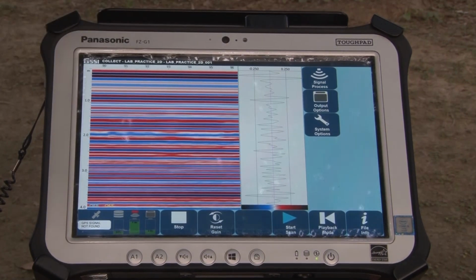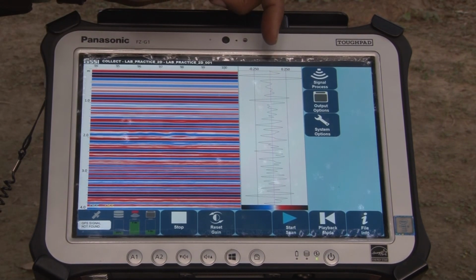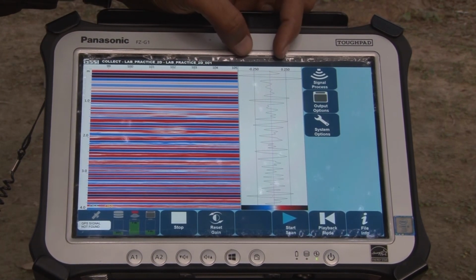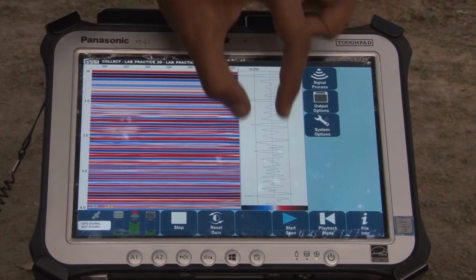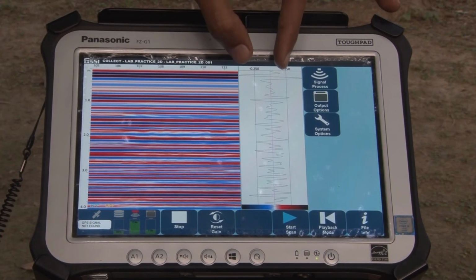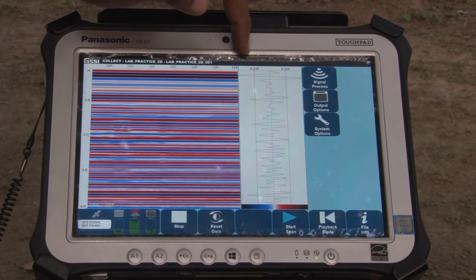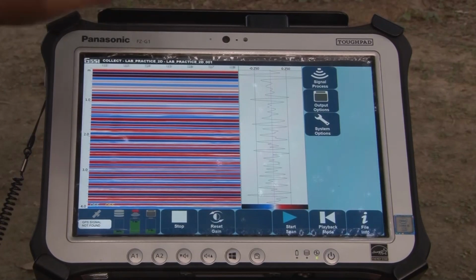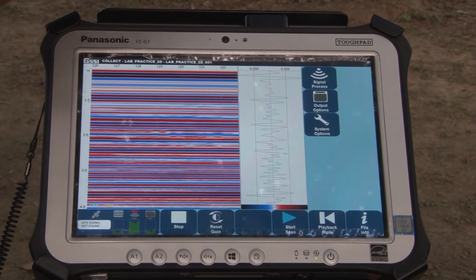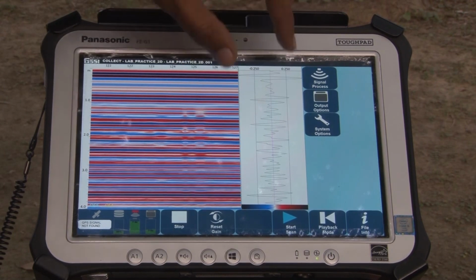So this is the propagation of the wave that we can see. The overall propagation is combined into one scan that we are able to see here. So we have to adjust the signal within this portion. Our signal should not cross the plus 0.25 and minus 0.25 bars that we are seeing. For better interpretation and better acquisition of the signal, we have to adjust it to between these bars.